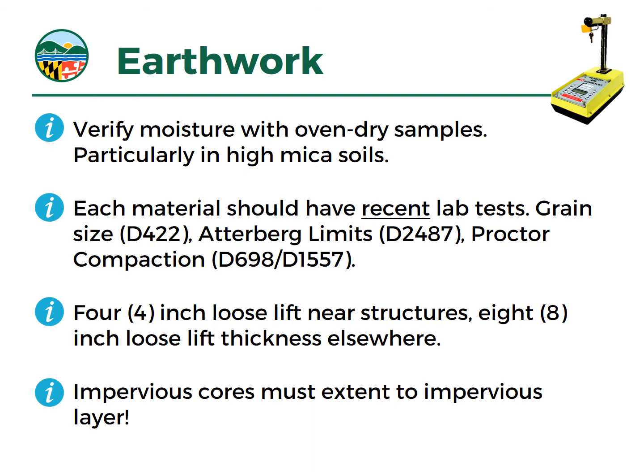Again, we mentioned previously on this last slide that recent lab tests are important. I've seen so many submittals from borrow pits or aggregate suppliers where they took a sample a few years ago when they opened up that pit or that material, and they keep on giving it to you. You'll see it in a submittal. The faxes they sent over and photocopied 10 times will be a little skewed and grainy, and the date might be scratched out or it'll be very old. But soil materials are variable. You don't want to rely on a really old test. You want to have something new and fresh for your site.